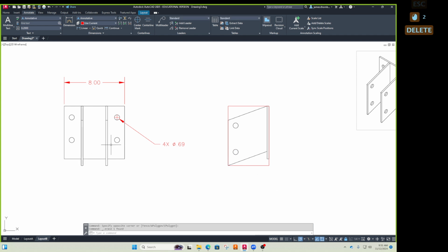So outside the part, if you can't do it outside the part, this part's pretty hard to fit it in the envelope, but sometimes with parts there's, you know, like a cutout or something like here. People want to put dimensions here. So you want to be outside the envelope. Right? Yeah. And so there's times we can kind of fudge those. If it makes it look better, then you can break those rules for placement. But we want to dimension holes where they're round. What are some of the other ones? There are arrows pointing to the center. That's going to be taken care of automatically here.